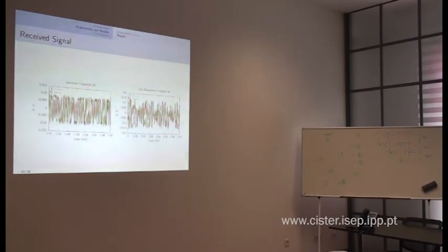But if you put two repeaters together, then we start to get this funny graph. And this is actually where we first started with this experiment. We saw this, and then from here everything else flew. So you can identify this. Does it look like something familiar now? This is the baseband signal of two nodes that are transmitting together. They have slightly different frequency, and they start to beat. And you get these depressions here. If the amplitudes were identical, then this would probably depress completely to zero. But it's not the case, and so you still have some signal.